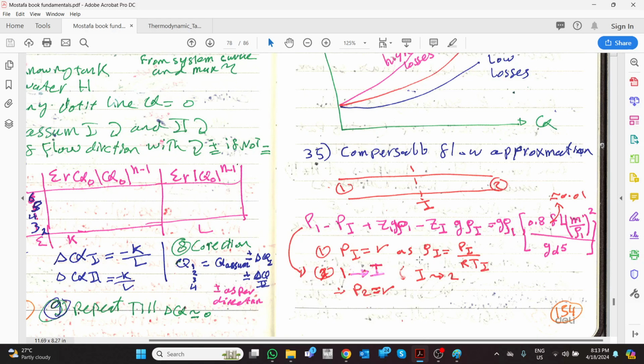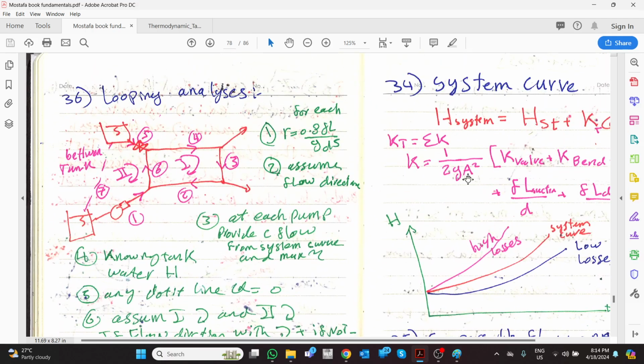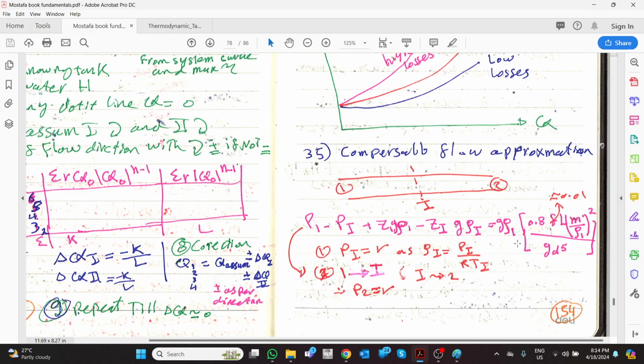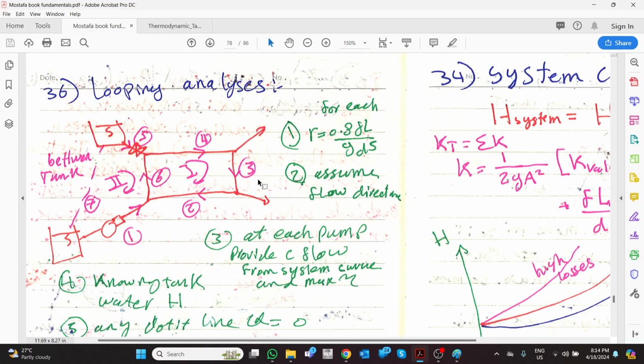From Pi, you know rho i equals Pi over R Ti. Then you repeat it again: 1 is now i, and i becomes 2, so from here to here you calculate the new pressure. When you make a lot of divisions, you can use Excel, or even software. Okay, it's just an approximation, by the way, for double checking.